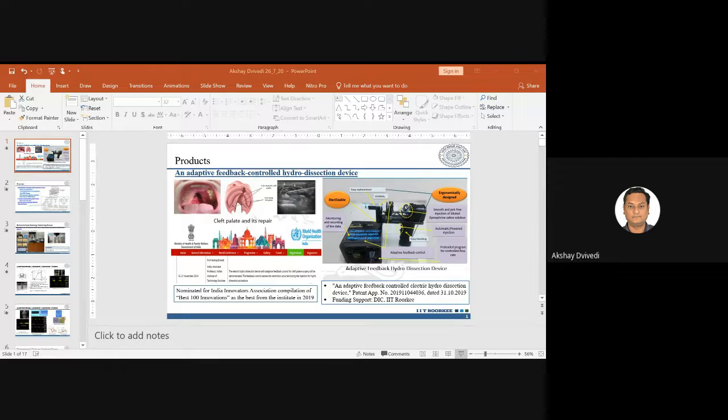The first one is with respect to a tool wherein we are using an abrasive coated tool. And the second oscilloscope image is with respect to a smooth tool, which is normal electrochemical discharge machining, no coating provided here. Now, here the oscilloscope image basically talks about voltage versus time. So basically here on my x-axis, I have my time, and on my y-axis, I have my voltage.